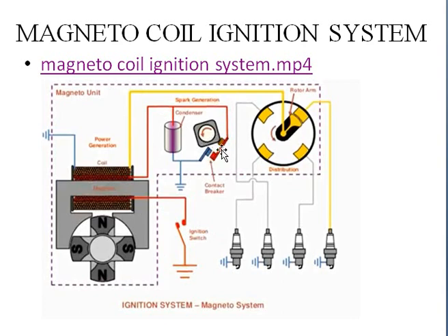So this is a camshaft. When it is rotating, when this contact gets contact, the circuit will be closed. Here also you have a condenser to control the spark that is produced here between both the electrodes. And now this electric supply which you are getting will be supplied to this rotating arm which is present in the distributor. This rotating arm will go in contact with the switching to the circuit which is connected to the ignition system. It means for the spark plugs. So now if it is in contact with the first one, the first spark plug will ignite. Similarly, 1, 2, 3, for all the things which you have.